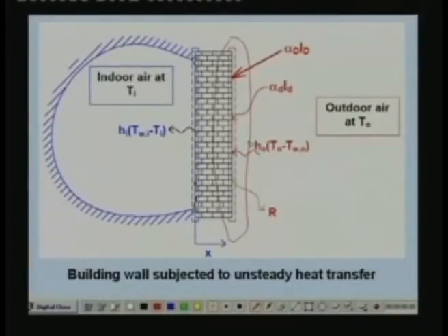What is the energy entering the surface? Energy is entering the surface by way of direct radiation, I subscript capital D multiplied by alpha D, where alpha D is the absorptivity of the surface for direct radiation and ID is the intensity of direct radiation. Similarly, you also have radiation reaching the surface because of diffuse radiation. So I subscript small d is the diffuse radiation and alpha subscript small d is the absorptivity for diffuse radiation.